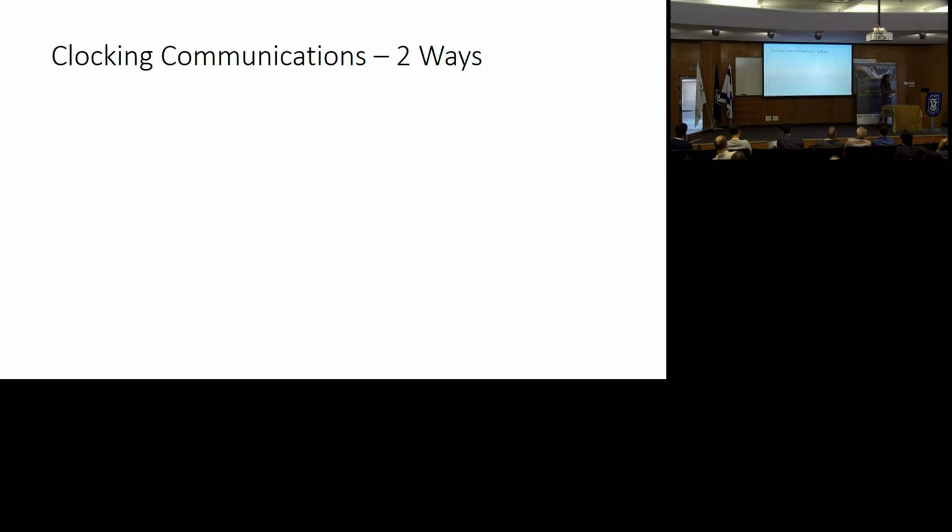Okay, so there's really 2 ways of doing this. The first way of doing it is asynchronous, and you guys probably have heard of this. There's been a lot of talk about wake-up radios. What a wake-up radio is, it's basically an asynchronous radio. It's an event-based radio that has 2 radios associated with it. One is the high-power radio that's actually going to do the communication, and the other is this latent, low-power radio that sits next to it, oftentimes just a receiver, and it waits.